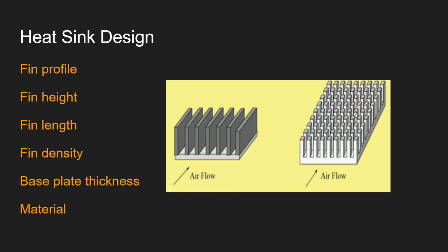We are not going to get into those details, but it does increase the mixing of air. You can see here that the airflow will not be smooth between the channels, and the airflow will become more chaotic in this case, which is actually helpful in increasing the heat transfer coefficient. So this is a better design.